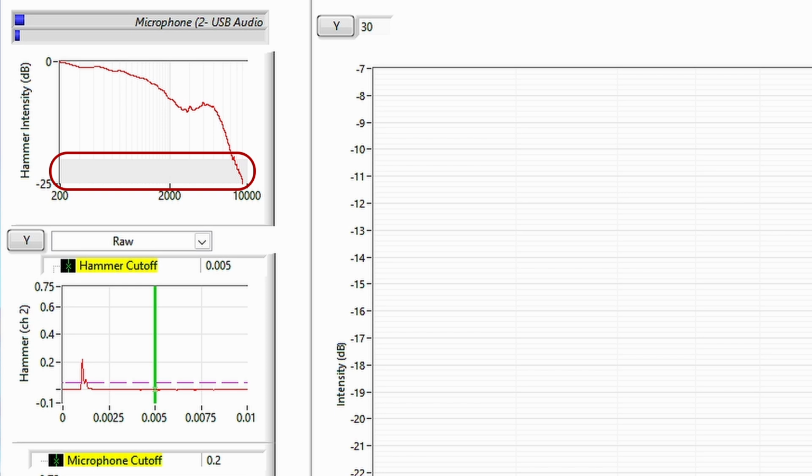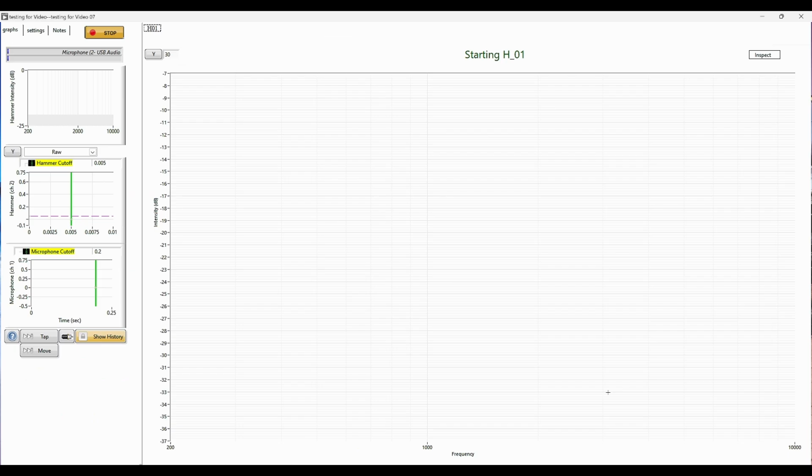We can see that our excitation signal drops into this area at about 7 kHz, so our measurements are good at least up to that frequency. Still plenty useful, but we should be careful and keep an eye out for this plot. It can often explain why you might have trouble with a given measurement. We will average multiple of these measurements to get more accurate results.